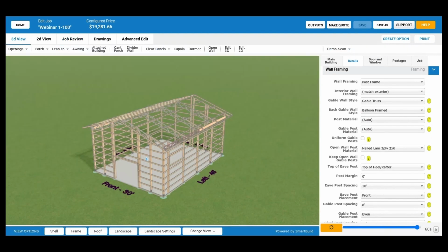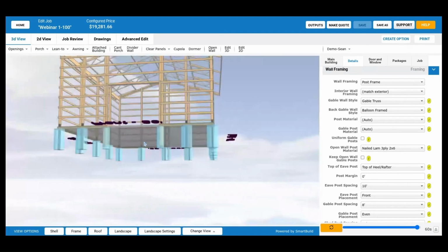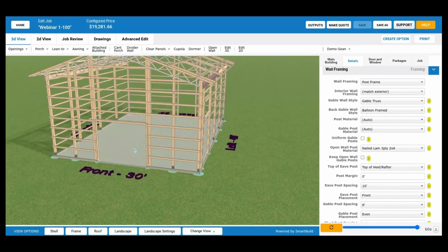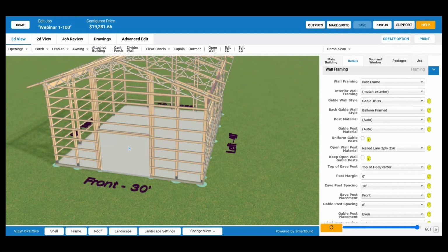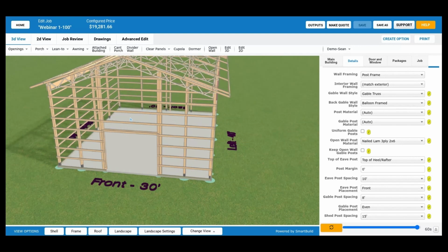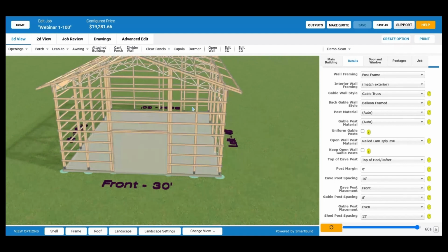And there's a lot going on here because there's a couple other things. Again, if we look at these jam posts, those are also the thing that triggers whether it is looking at individual posts on the gable walls through those span tables, looking at the heights of these individually, or just using a single material for all of the posts on your gable wall.